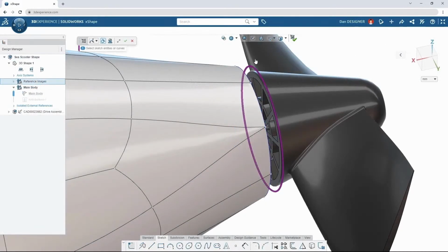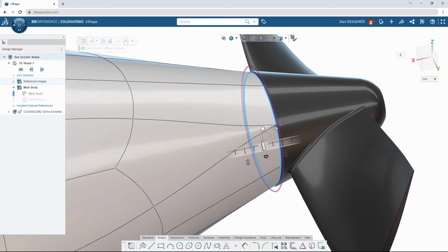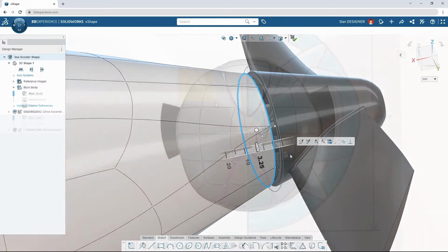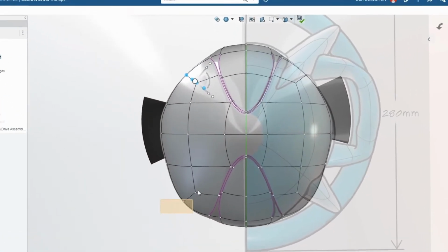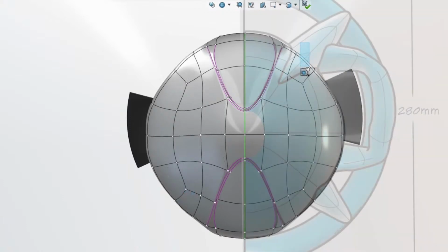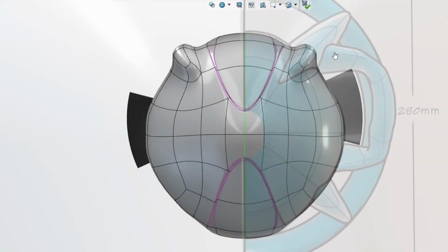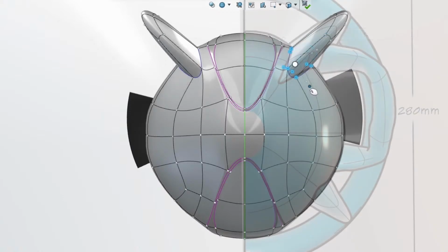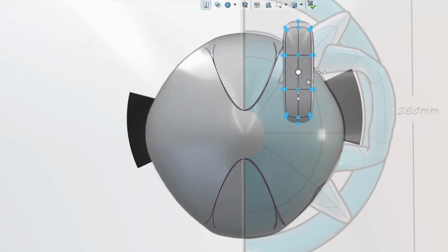We have a sketch that we have to align the subdivision model to, so we can align that right to that sketch. And we can also choose how much of an offset with a parametric dimension added to that. Then you can also see symmetry is being applied, where we're changing one side and it's automatically updating the other. And we can extrude additional material as well. So you can start adding more and more material as needed.